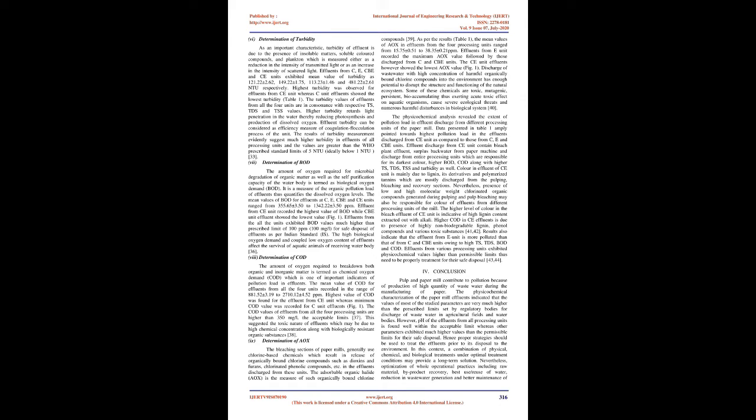4. Determination of TDS. Total dissolved solids, TDS, is a measure of the combined sum of inorganic and organic substances contained in a liquid, which primarily includes minerals, salts, and organic matter, which can be a general indicator of water quality. In the present study, the highest TDS was found in effluent samples from CE unit, 3032.14 ± 3.32 ppm, followed by E, 2218.66 ± 2.64 ppm, and CBE, 1704.32 ± 5.35 ppm, units. Effluents from C unit however recorded the lowest, 1518.27 ± 2.65 ppm, TDS, Fig. 1.